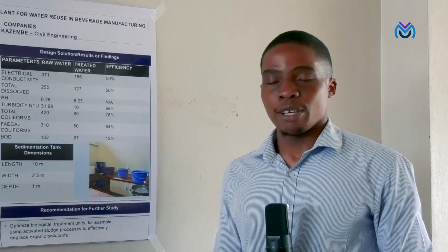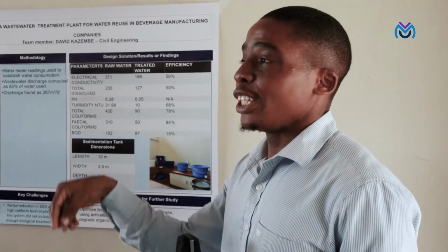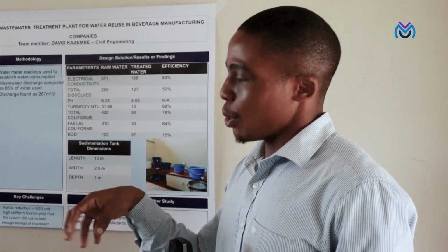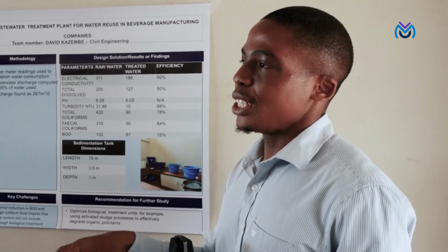So in terms of scaling up, essentially it's incorporating the aerator. The aerator is like a propeller. It propels one of the tanks. It allows air coming in. So as the air is coming in, microorganisms have more oxygen to digest any organics that are in the wastewater. As such, as the organics are being digested, you have a lot of contaminants being removed.